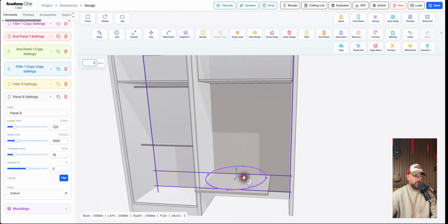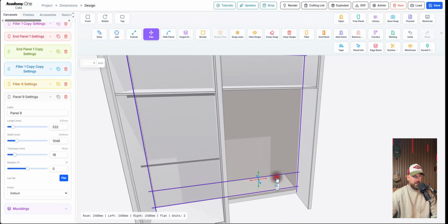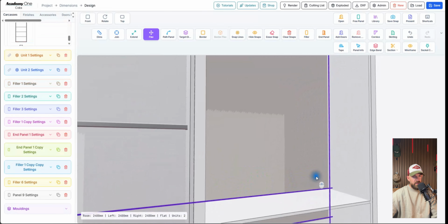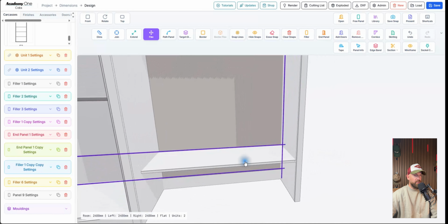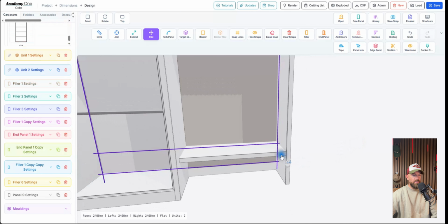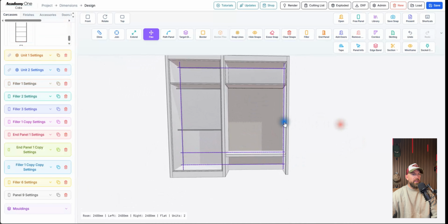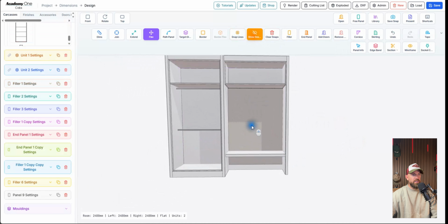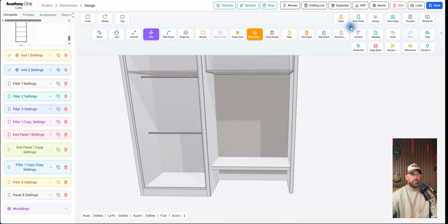That's cool. Just going to bring it over, snap it into the side, grab my flex tool again, push that back and extend it over to this side, and then that is going to sit there. I quite like the fact that that's sat back on the filler a little bit, so that's quite nice. And then I'm going to create maybe like a 50mm thickness on this. So that's that bit done. And then what I had, I'm going to just hide those snaps again. Then I had some slats in this. So I'm going to put those in.